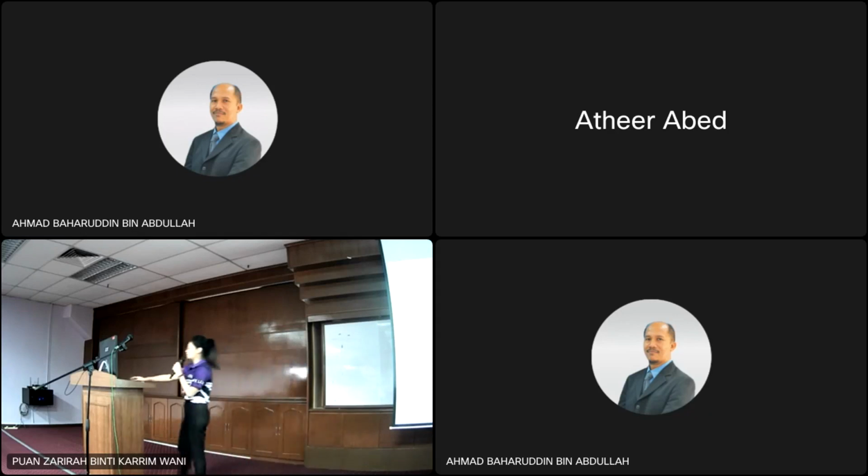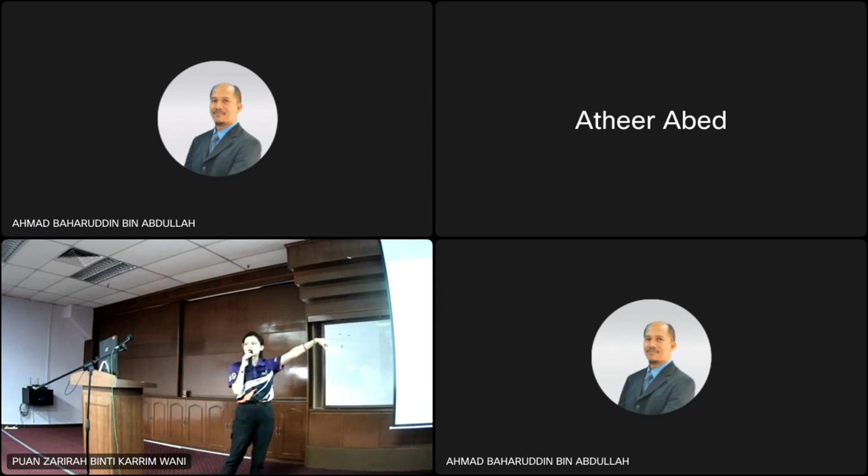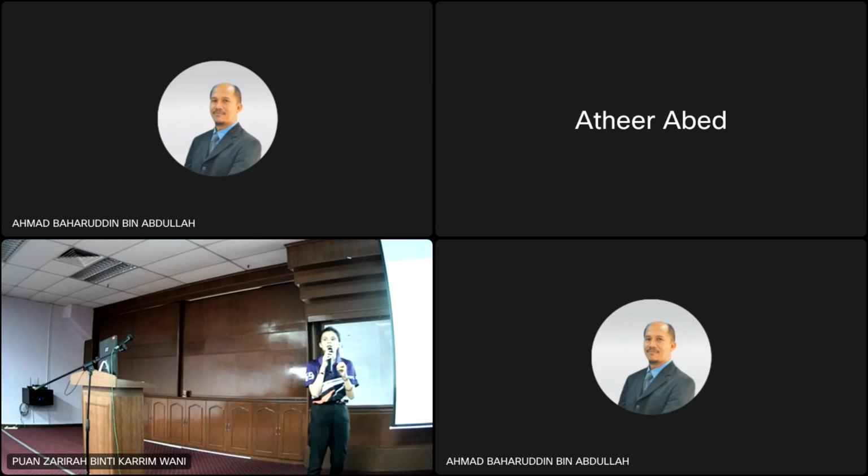So here you can see the example of the G-code. On the left side is the example of G-code for the full assembly, and the right side is the example of G-code for the problem feature part. Before we convert both G-codes, the first thing that we need to know is the name of the problem feature part. We named it wave B1, so we can directly search for wave B1 in the full assembly G-code by using Control F.